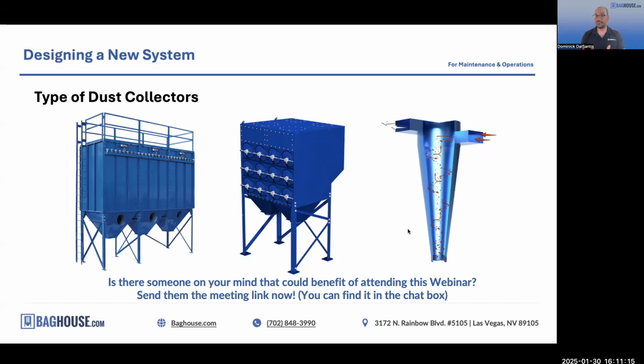You also have the option of pleated filter bags, which are kind of a mix between the benefits of a bag house and the benefits of a cartridge collector, kind of like an SUV, right? So they have some of the benefits of more filter area like the cartridges, so the bag house is smaller, but they're not so tightly packed like the cartridges. They're more like bag houses in that sense, where it's bigger, easier for the dust to fall off. So you can use them in a little bit more difficult applications that a cartridge wouldn't use.